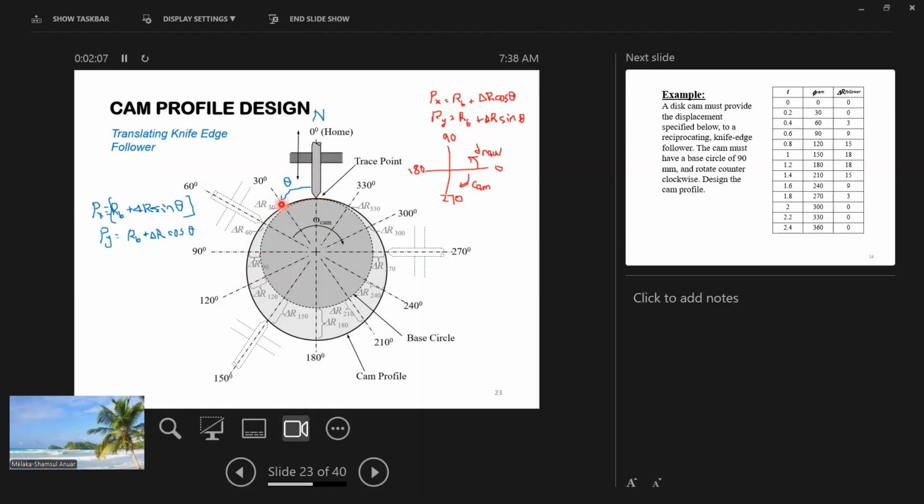So this one creates points every 30 degrees of rotation. So 30 degrees will be here. As you see, this one will be delta R at 30 degrees. Okay, so you have to go back to your displacement diagram, get your delta R at 30 degrees and draw the point over there. So this one at 30 degrees, get that point, 90 degrees, 120, and so on and so forth. All right, so this is a situation where it is inline.